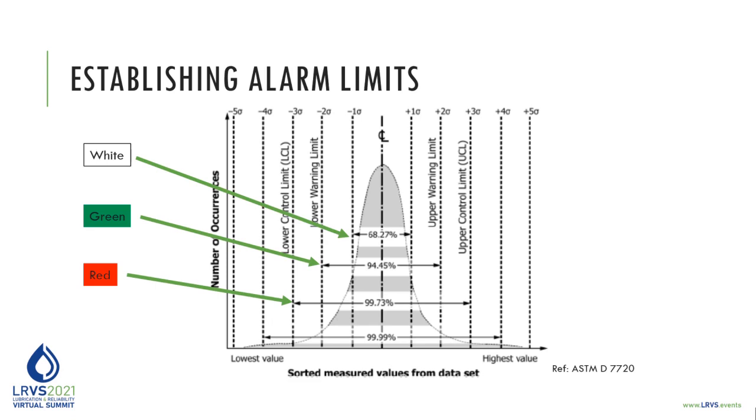Some tentative alarm limits can be set though with the data population, as small as maybe say 7 to 10. In these cases where all the identified failure modes and causes are not necessarily represented, lower quality alarm limits will still result. Now these alarm limits can manually be adjusted upward through experience according to similar machinery that you have. In cases where failure modes and causes are overrepresented, some higher alarm limits will result, and that's alarming.